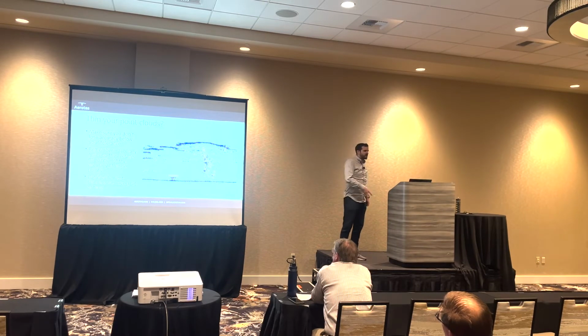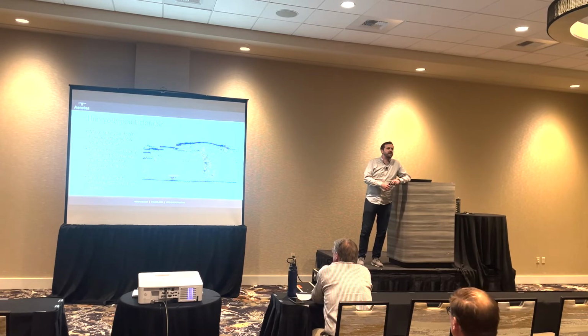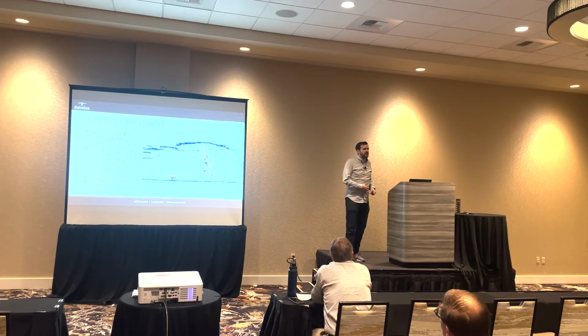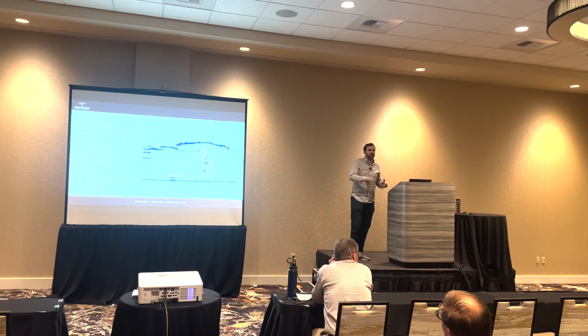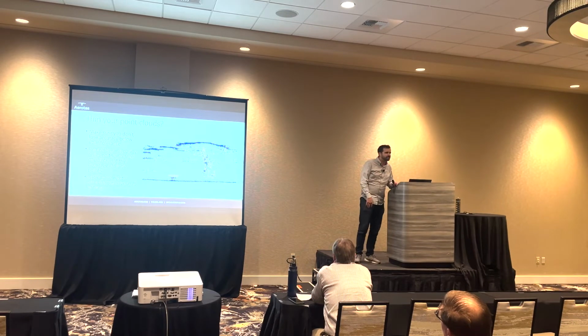The only cases that we actually do thinning, at least in our internal workflow, is after we've classified a point cloud. If someone needs a classified point cloud as a deliverable, we might thin, for example, the vegetated layer, the vegetated class, because trees, you can thin that and you can say, okay, instead of 200 million vegetated points, here's 1 million vegetated points. Brings your point cloud count down a lot, still very reliably tells you where the trees are. Whereas for something like a power line, you wouldn't want to thin that at all because that data is a lot more reliable.